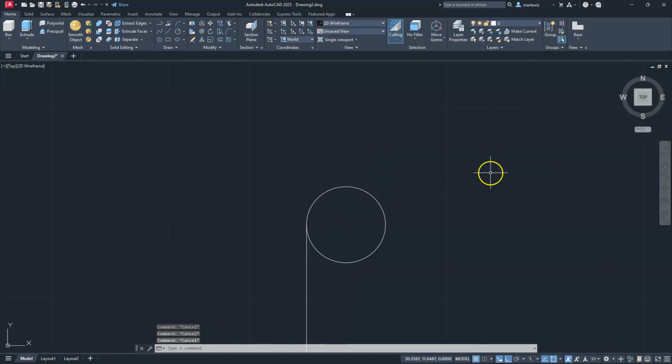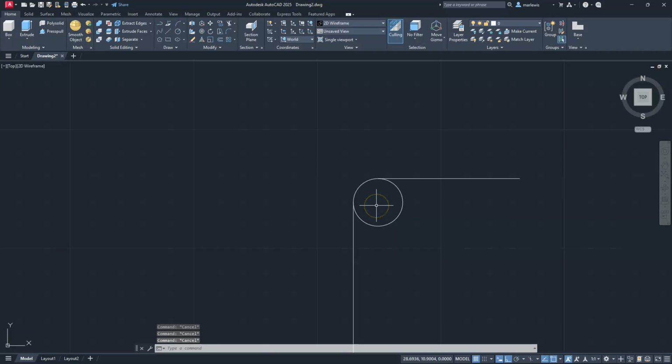Now for this line that's going at 100 degrees, what I'm going to first do is draw a line from this quadrant going out this direction, a distance of 2.866. Then I need to rotate this, right? So I'm just going to use the regular rotate command. I'll select my line. I'll go from this base point. It looks like it didn't rotate. So rotate that line from this base point. And remember, counterclockwise is positive here. So I need to just spin this up 10 degrees.